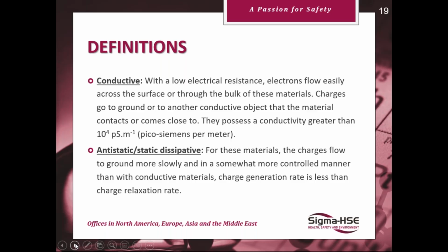Anti-static, static dissipative. For these materials, the charges flow to ground more slowly in a controlled manner, and then the conductive materials. Charge generation rate is less than the charge relaxation rate. In other words, you get rid of the charge faster than you can build it up.